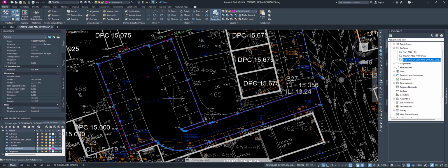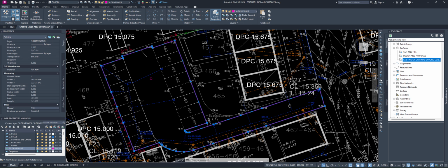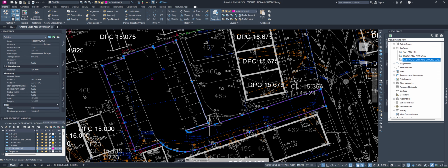It's important to create a looped model, or closed polyline work model, if you're going to create a surface from that line work. Okay, next step is converting the polyline from type polyline to type feature line. Object of type polyline to object of type feature line.